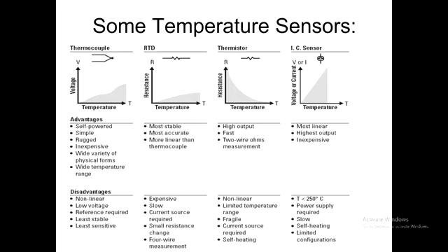When you're running that current through, it's I squared R type heating. You know what I mean by I squared R heating? Power in a resistance is equal to current squared multiplied by resistance. If you don't know how that works, just think back to Ohm's law and use it twice, and you'll get the answer there. So that brings an error associated with it, and you have to use judicious choice of what you run through them.